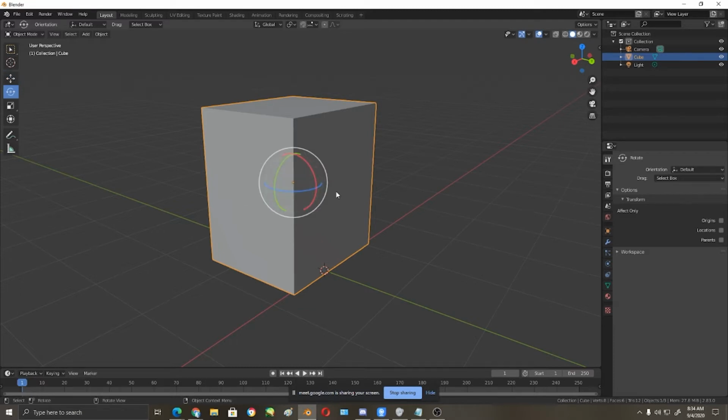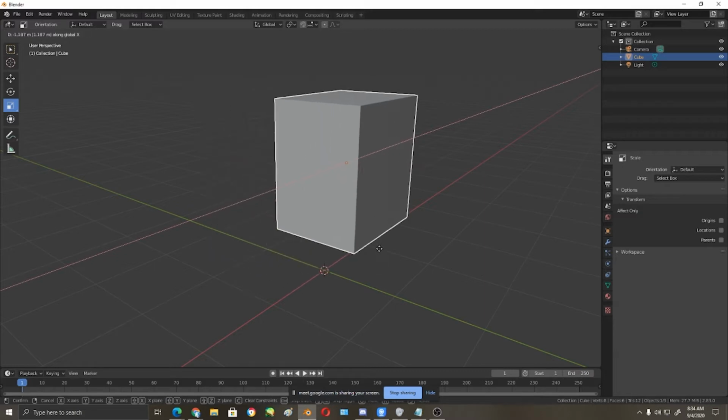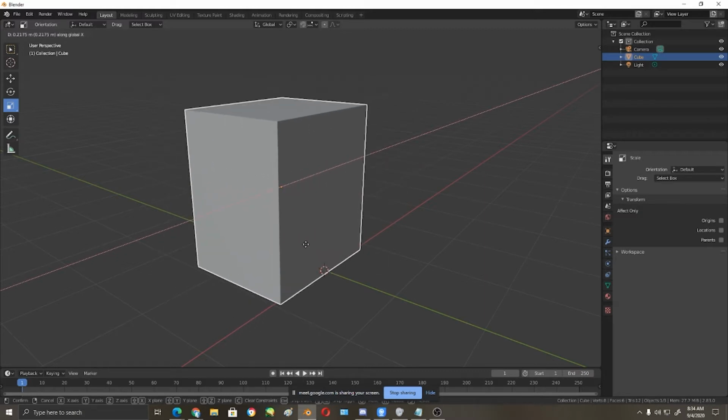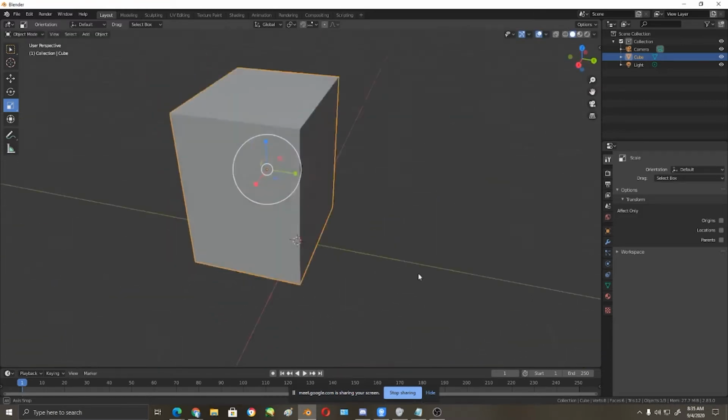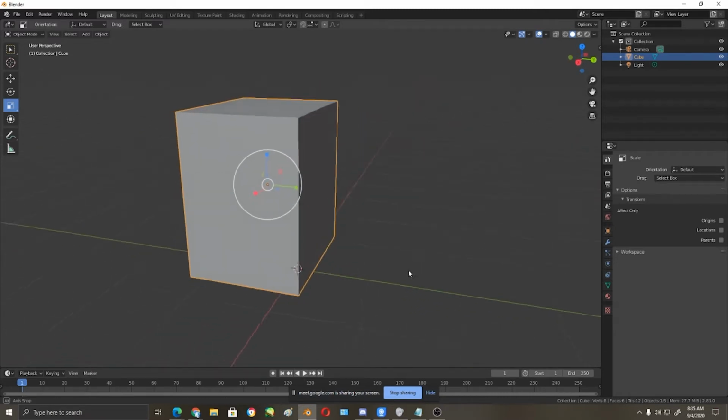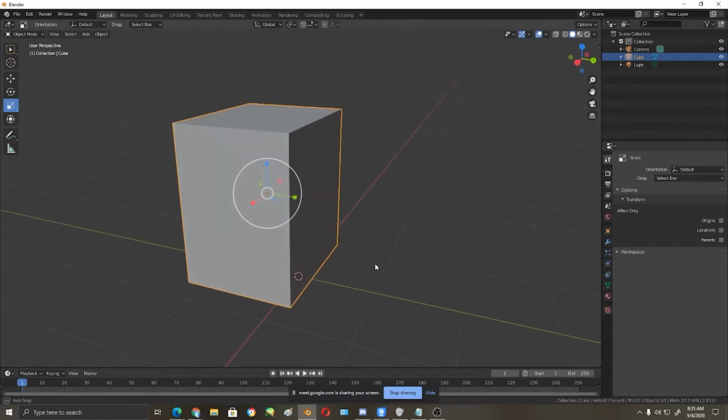So it's very convenient that I would just move a gizmo instead of memorizing the X, the Y, and the Z. So I'm very visual, so that's what I use. But you can also use G, S, and if it's not in the X direction, you just go to G then Y. Alright? So those are some of the ways that you can manipulate the objects.